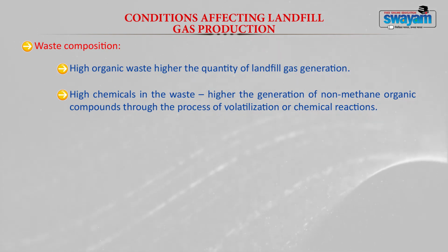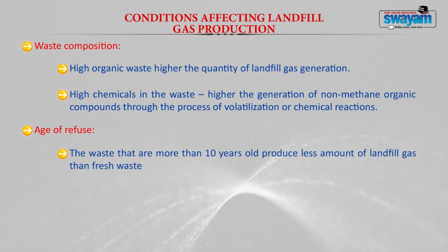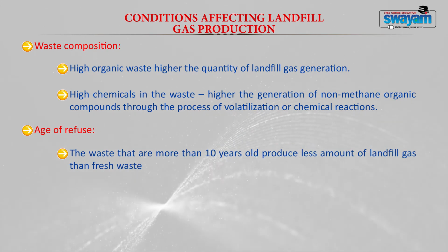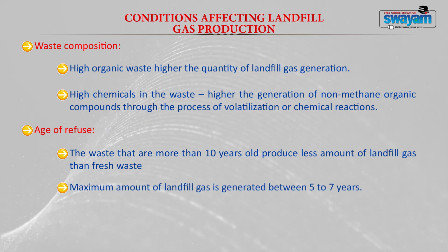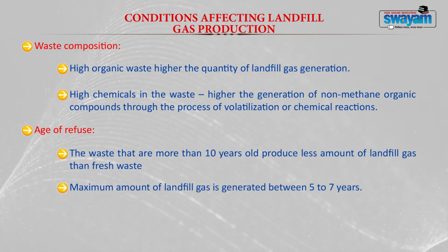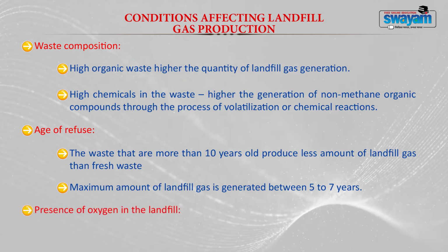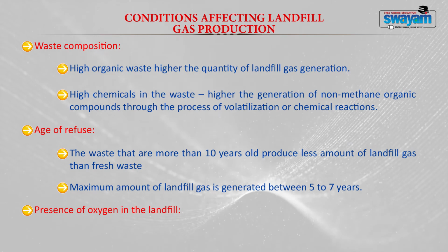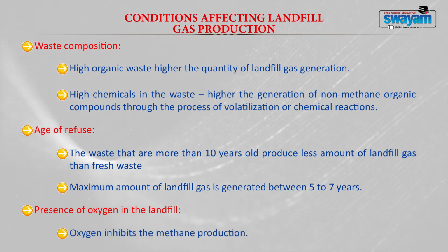Now, the second factor that influences is the age of refuse. Waste that is more than 10 years old will generate less landfill gas. The maximum amount of landfill gas is generated between 5 to 7 years of waste loading. The presence of oxygen also inhibits methane production or indirectly alters the composition of gas.